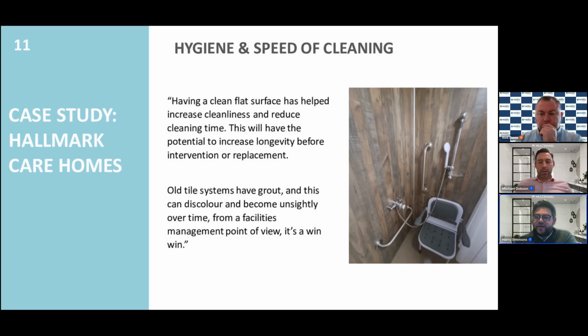So I've just seen a question come through about vinyl flooring. So yes, you can fit your wet room style vinyl flooring. We have a trim that clips onto the bottom of the panel and then caps around, so you can fit your flooring underneath the trim. Because you have to replace the flooring a lot more often than you have to replace the panels, it allows you to replace the flooring without having to touch the panel. You can slip it back under from the trim and then refit your new flooring. So it makes the whole process nice and easy.